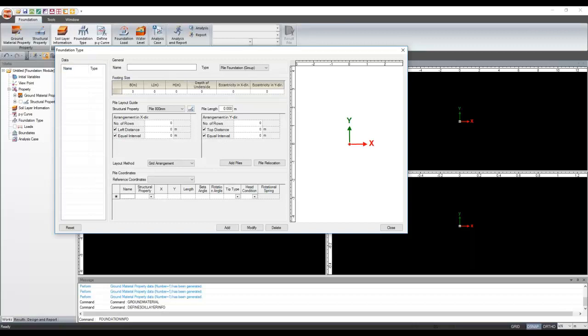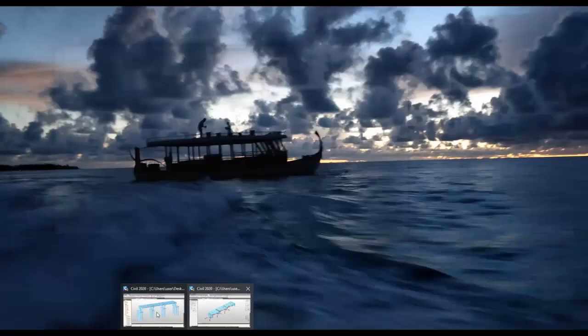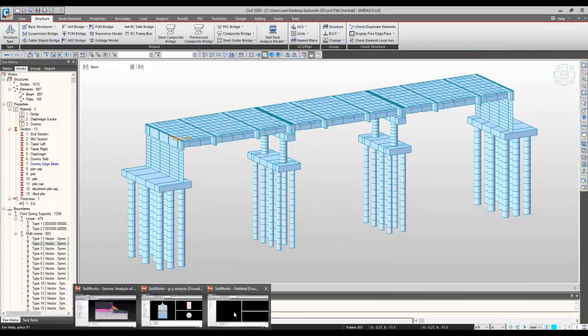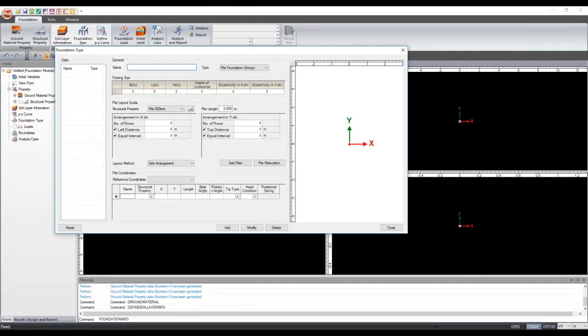So as I said, preliminarily we are going to go for this abutment. The very first one is your 3x3 piles, and we'll be defining these particular parameters in the software now. As you can see, we are not modeling them, but we are just defining the inputs in the software. So let's say the first one is given the name abutment.